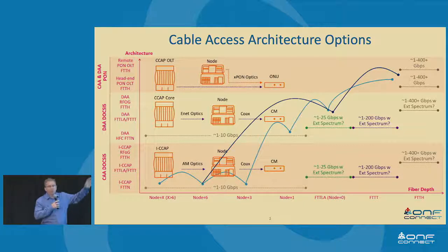The optical transport becomes all digital now. That's a fantastic gain for the operator because it returns a ton of optical domain for use for any other kind of digital service, right? And so upper C-band and L-band all now available for DWDM, CWDM services, whatever the operator may choose. And some operators will also bring into the same path PON services as well. There's certainly ways to mix and match that into place.